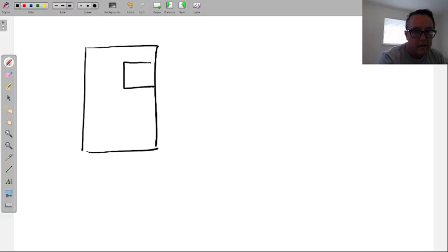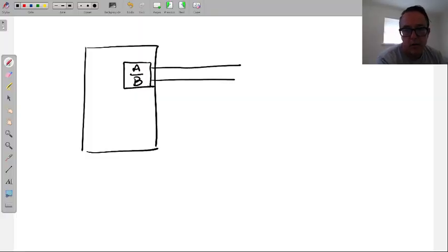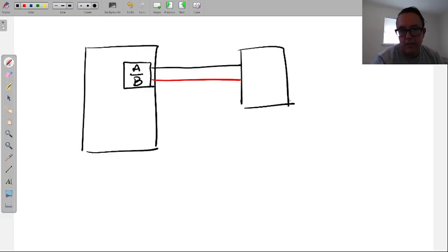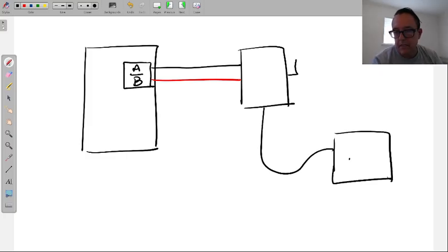But this disconnect switch, let's say it's a 2-pole, A phase and B phase, and we head over to this. Let me change the conductor wires to keep them A phase, B phase colors. And we head over to this disconnect switch. And now this disconnect switch feeds our, let's say, air conditioner that sits outside.